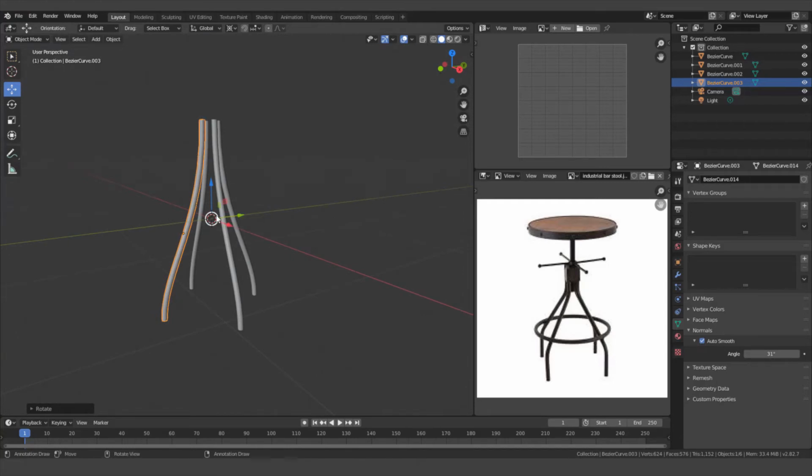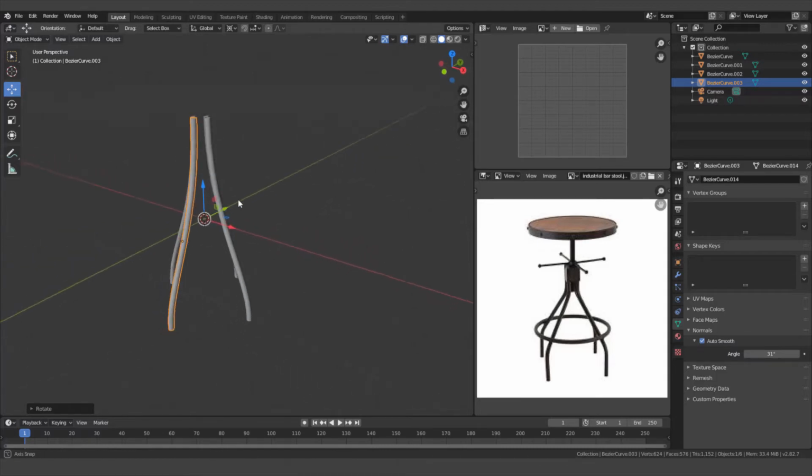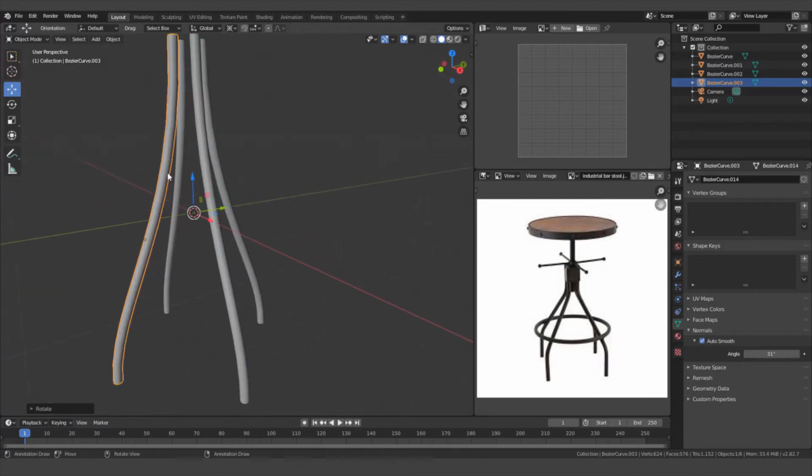They've been smoothed. That's the basic workflow of this project. Each part we make, we're going to model it, we're going to unwrap it, we're going to smooth it. And then once we smooth it, if we need more than one of those, then we can duplicate our objects with all of those attributes. Otherwise, you have to kind of go back in and redo all that stuff. So it's best to just do it to one object before you duplicate and go on.